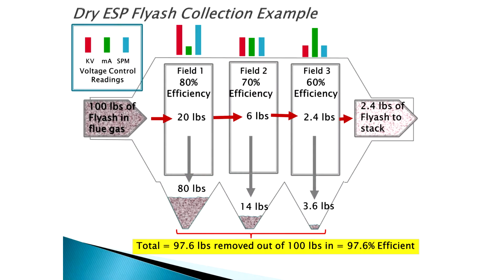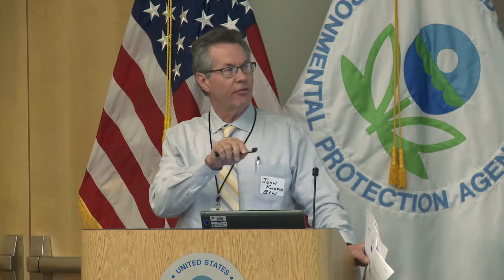Very good. Exact answer. If you examine the dust collected in the inlet hopper there, it's mostly the large particles, because fine particles need a longer time to achieve the charge to remove them from the gas stream. So the fine particles are mainly caught in the outlet field.